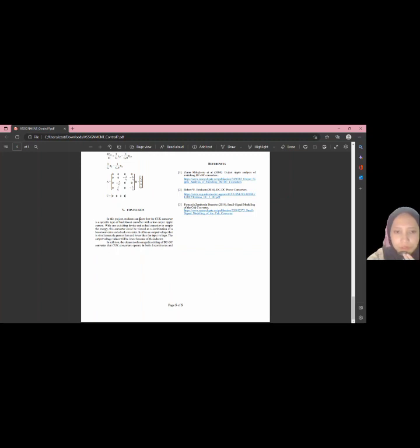For the conclusion, in this project, students can learn that the Cuk converter is a specific type of buck-boost converter with a low output ripple current, with one switching device and a dual capacitor to couple the energy. This converter could be viewed as a combination of a boost converter and a buck converter. It offers an output voltage that is simultaneously greater than the lower input voltage.